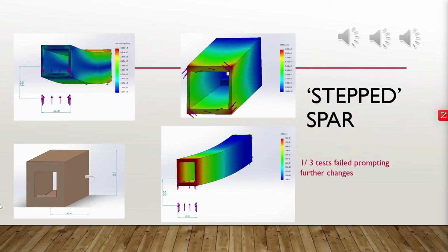There was again a discrepancy between SolidWorks and Excel with the necessary width criteria, where Excel only required 40, the SolidWorks required 42. Interestingly, although the linear stress gradient would have suggested that the step should have been made 200 millimeters from the tip, due to the fact that there were concentrated stresses in the far corners near the root, and the linear stress gradient only began further forward, it's actually allowed us to take that step at 500 millimeters in, really reducing mass greatly. Unfortunately, the displacement test was a failure.